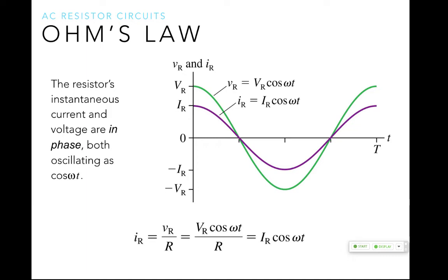Let's say your voltage source is from the wall, okay? What's omega? It's the inverse of the frequency. Yeah, it's the angular frequency, but what comes out of the wall? What frequency? It's 60 hertz, right? 60 hertz times 2 pi, so omega would be 120 pi radians per second. Okay, that's because it depends on your voltage source. So omega comes from your voltage source.